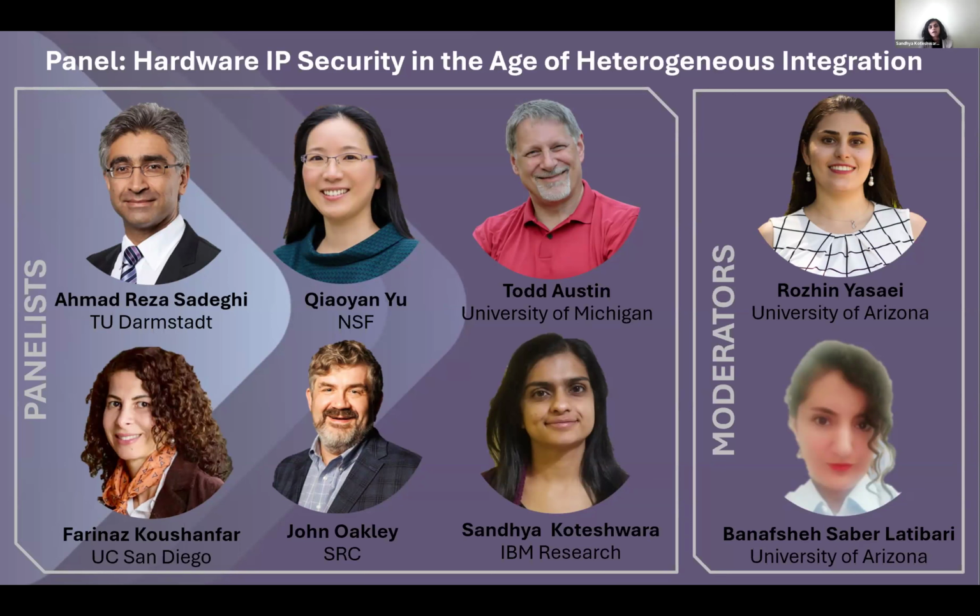Can it collect measurements from the chiplet so that the entire SIP can be attested before that SIP is let into a larger system, right? Things like that. We're looking at it and the interface between chiplets. UCIe primarily looks at defining the physical and the link layer of the connection between chiplets. What we would do is add things like integrity protection into the packets as they travel, right? So things like that.